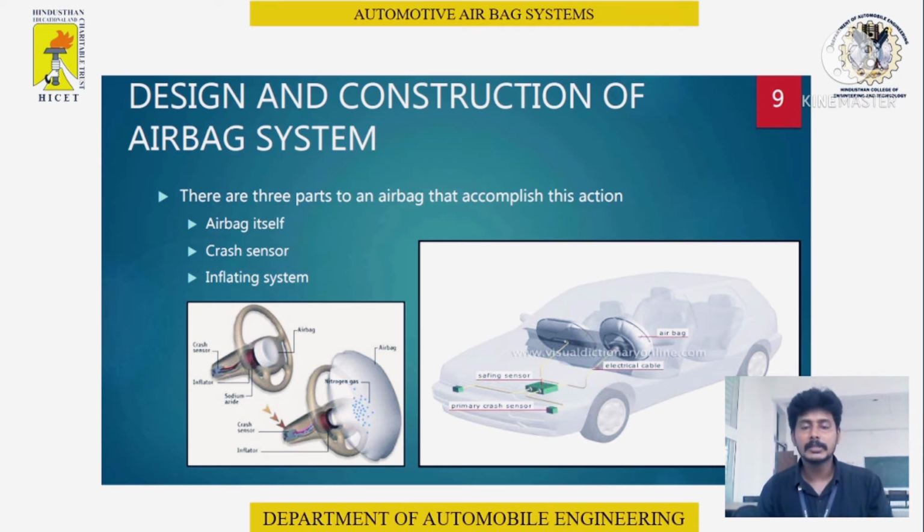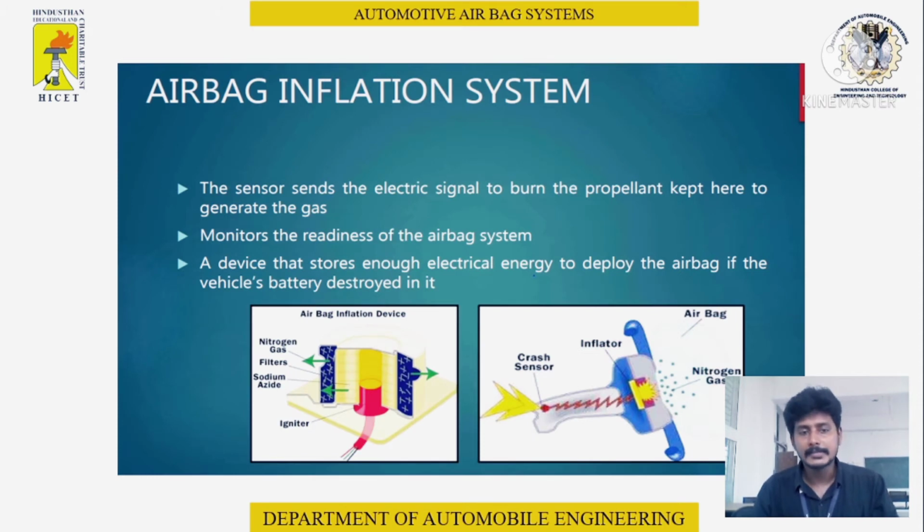Next, design and construction of airbags. The important parts of airbag systems are three: the airbag itself, the crash sensor, and the inflator. In the airbag inflation system, the sensor sends an electrical signal to burn the propellant kept here to generate a large amount of gases.